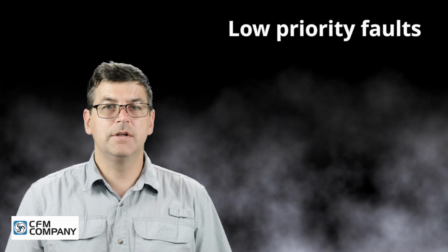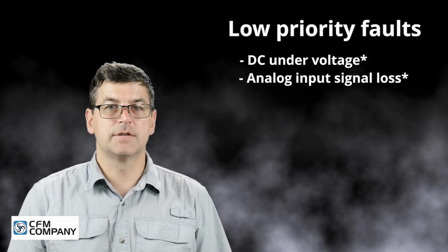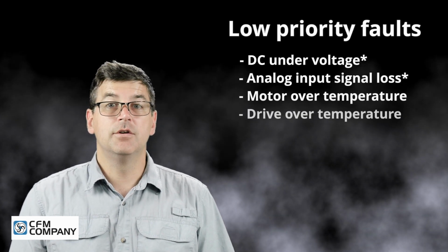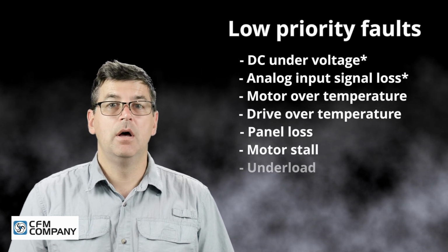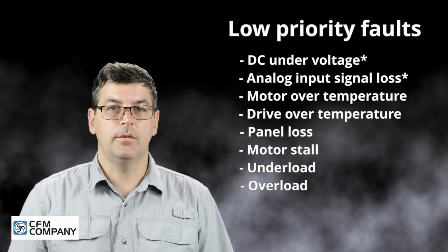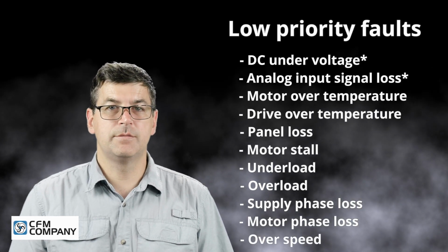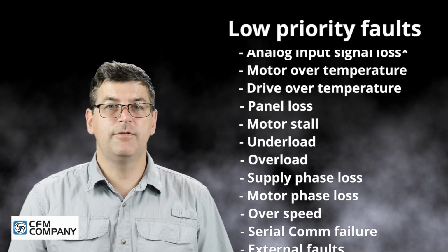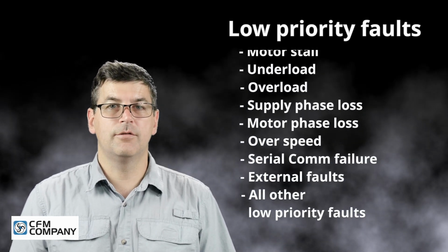Low priority faults include DC undervoltage, analog input signal loss, motor over temperature, drive over temperature, panel loss, motor stall, underload, overload, supply phase loss, motor phase loss, overspeed, serial communications failure, external faults, and all other low priority faults.